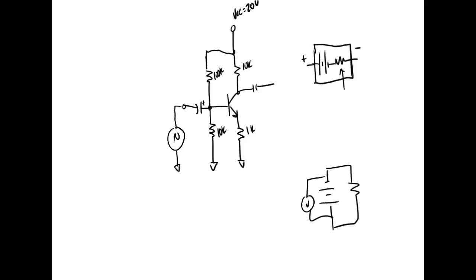You understand? Now a signal source, a source of a signal. So remember, we got two things. This guy here does not create power. Where does the power come from? The power comes from that power supply right there. That's why it's called a power supply. So transistors do not create power. They just control it, right? So when we say we got power gain, if I've got a 100-watt power gain, then by George, I've got to have a power supply that can provide that 100 watts. So transistors do not create power. They just control it, right? You understand? That control current.